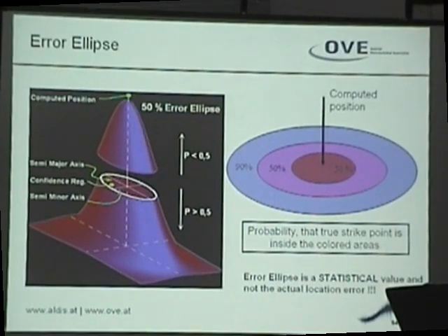Because we don't use the time standard deviation, we use the root mean square. In the root mean square, there is a part of the systematic error you move to this value. So we increase the time standard deviation artificially to have an appropriate error ellipse. Was this clear? I'm not sure. So you work on the safe side. You increase the error in order to have it random.